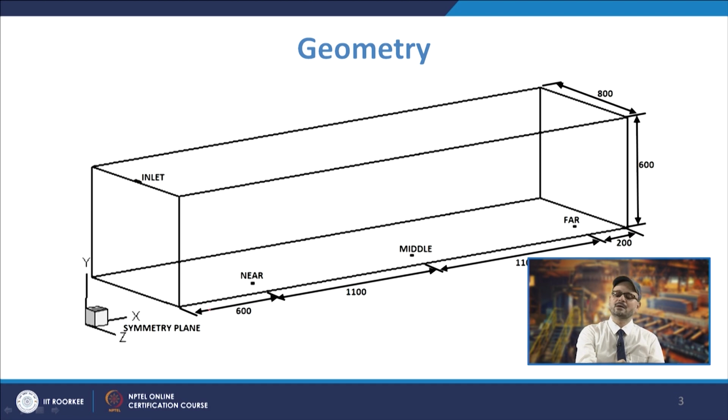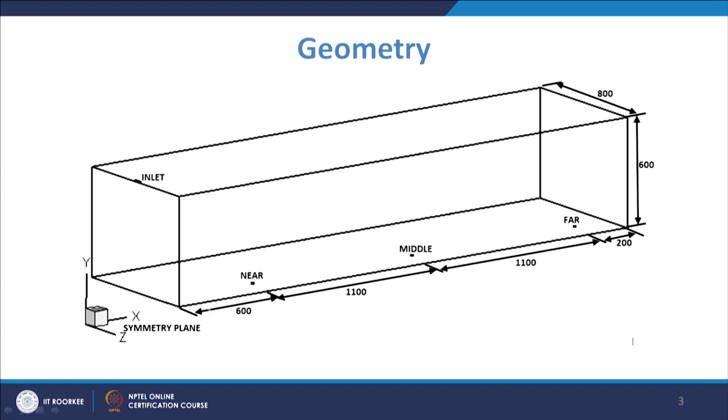In that case you have to make this geometry. In any modeling tool, you can create these geometries by taking points at different positions, joining them to form edges, then creating the surface, and then creating the volume. Similarly, you have to identify these areas, like the inlet and the outlets. That way we create these geometries for the Tundish.